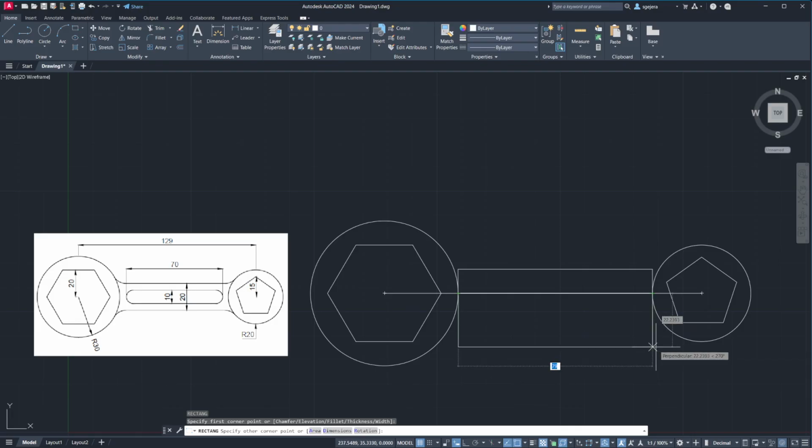Notice how down here, there's a green dotted line, or green dash line. That is our tracking line. In most tools for AutoCAD, it can track certain elements. It could either be a node, perpendicular distance, or parallels and extension lines.